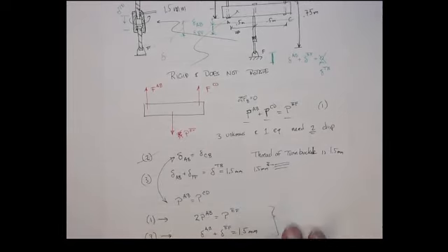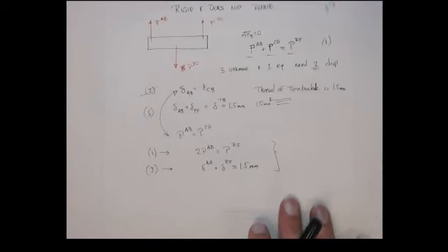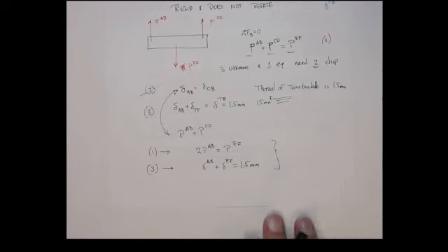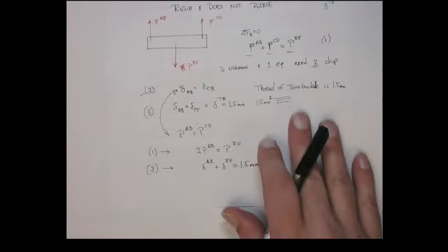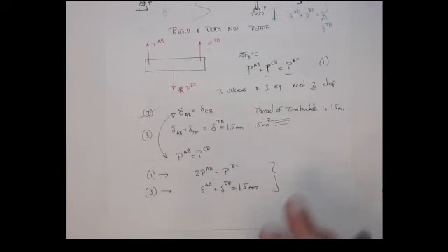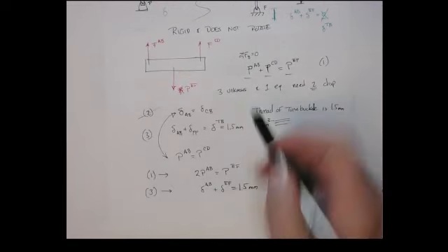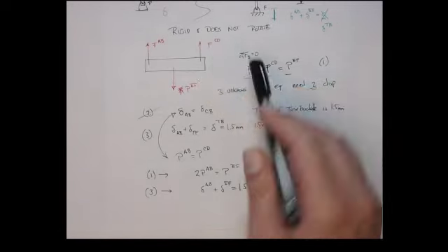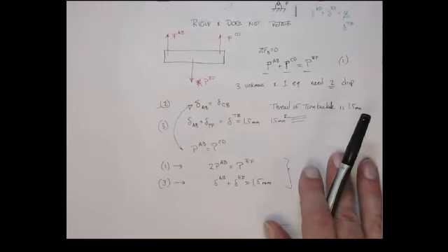And it's usually very difficult to do something like that, especially on something like an exam. Okay, so I always recommend that. Assume positive elongations. Elongations are positive values of delta, and assume that internal reaction forces are positive in tension. So that's why I drew these forces this way, and you can see that affected my sum of forces balance.